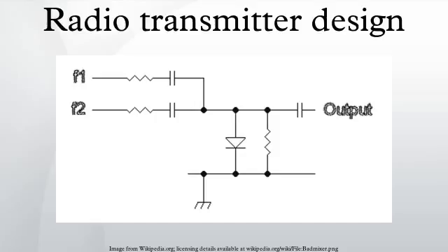Low-level and high-level. In low-level modulation a small audio stage is used to modulate a low-power stage. The output of this stage is then amplified using a linear RF amplifier. The great disadvantage of this system is that the amplifier chain is less efficient, because it has to be linear to preserve the modulation. Hence high-efficiency Class C amplifiers cannot be employed, unless a Doherty amplifier, or other methods of predistortion or negative feedback are used.